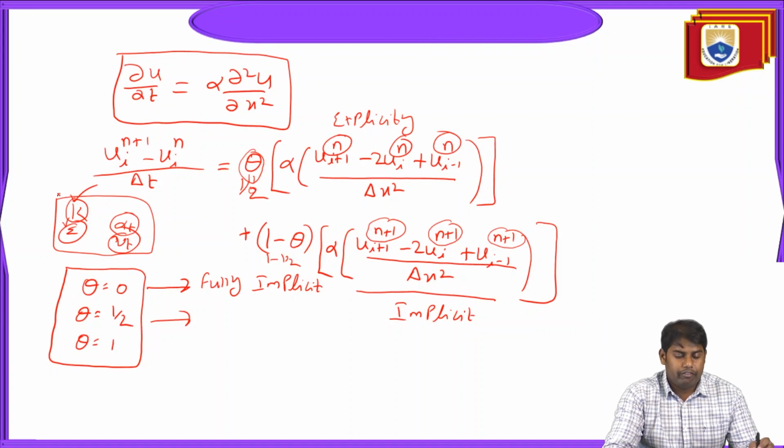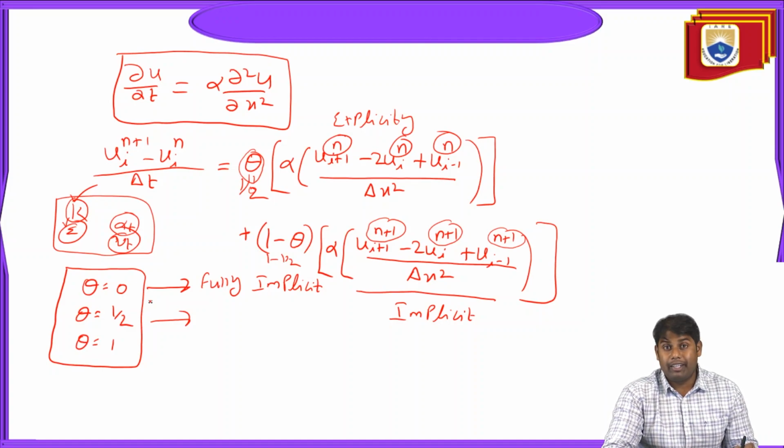So when we are using the switching factor half, semi-implicit, half explicit will be done and half implicit will be done. For the half implicit part, initially we will switch the values of K, alpha T, epsilon, nu T with the initial conditions. Once we get those values, we will substitute them in the implicit scheme such that we correct it and reiterate it again. So this is what we do. This is one generic process which I am explaining for the semi-implicit method. There are other numeric or more detailed explanations, but this is the generic way to explain the semi-implicit method.